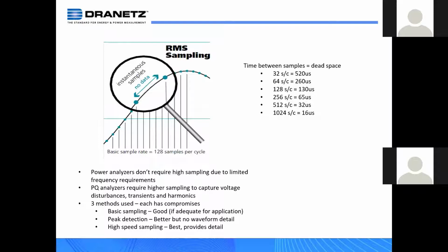We do have products that digitize all the way up to 1 megahertz. That would be our HDPQ Plus Explorer, or HDPQ Explorer Plus instrument, and the Explorer SP. That's meant for more advanced applications, but nothing's going to go past that instrument. It digitizes to a microsecond. So really, this 512 samples per cycle, just kind of a rule of thumb, will get you maybe 75, 80, 85% of all power quality problems, where the Explorer level product in our product line will get you virtually all of the rest of the power quality problems.